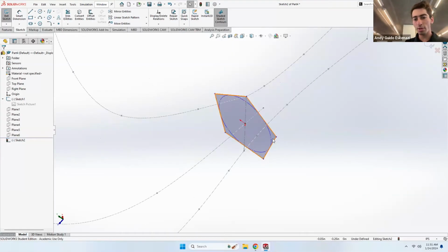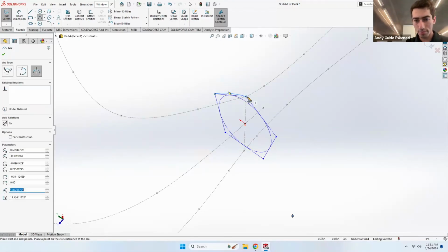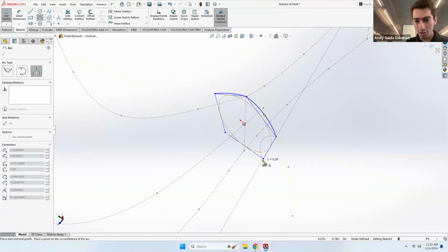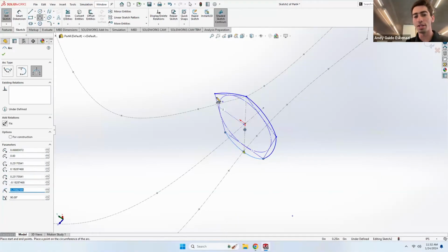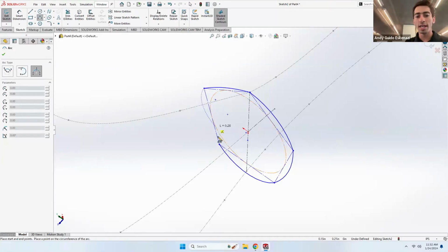And the next thing I'm gonna do is I'm gonna right click on the pentagon and I'll make all of those construction geometries. Now, because a banana is more of an organic shape, I'm gonna click on all of those sides and make little arches all the way like this. And this banana, the one that we're gonna design, is gonna be pretty symmetric in the sense that all of these pentagons, with the exception of the arches that I'm drawing right now, will be equal, they will all have the same side length.